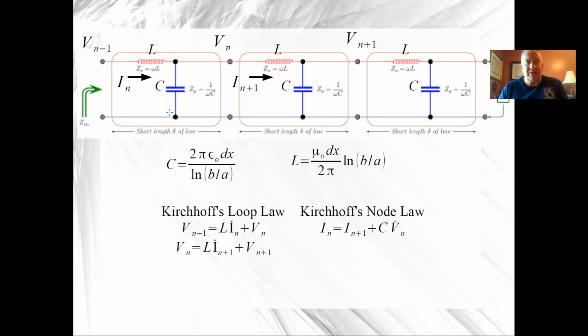In chapter 2, we said that the current that flows through the capacitor is equal to the capacitance times the time derivative of the voltage. So if the voltage across the capacitor is increasing, then the current is positive. If the voltage across the capacitor is decreasing, the current is negative. And if the voltage is constant, no matter how great it is, the current is 0.